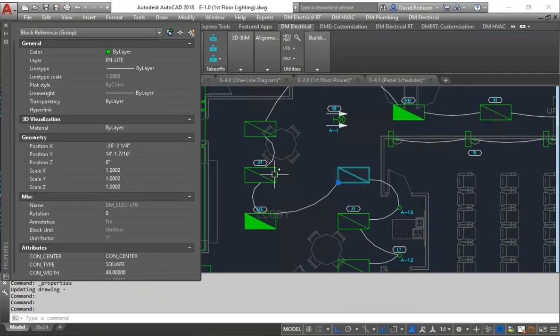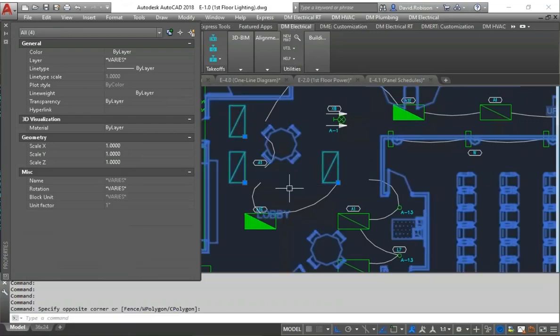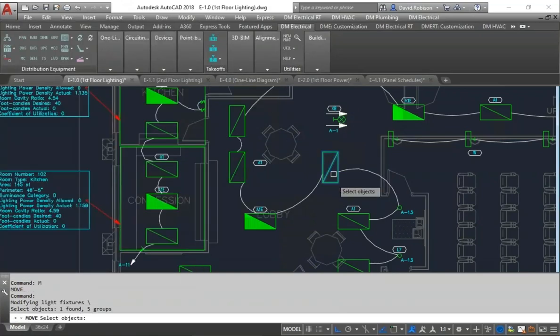So having said that, you actually could select them and then use just the AutoCAD properties to rotate them 90. So you can do something like that. Oh, there. We had to run a command, and there we go. It updated. As soon as you update the properties dialog, we don't get alerted that something's changed. But as soon as you run a command, it sees that something has changed, and then it reconnects all the loops for you. So if you need to rotate multiple things, that's more of an AutoCAD drafting question. You just handle that in whatever way you would like to handle it in AutoCAD.